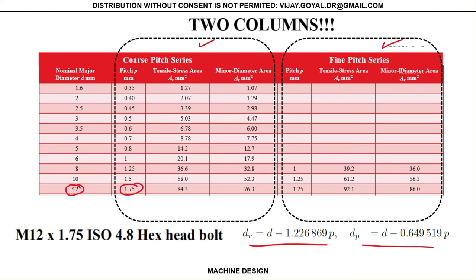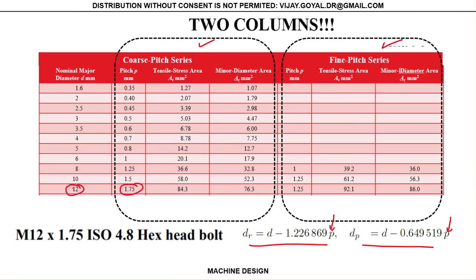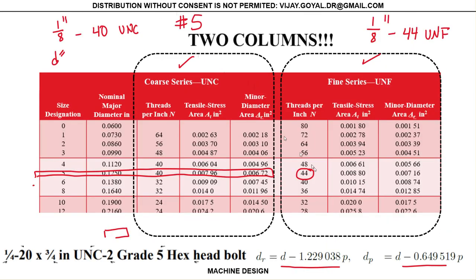Okay, and in this particular example, in this particular screw, this is easy to find because you already know this, and this is given by the pitch diameter, so just use this equation. Okay, and note that the number is correct, but the only change is this one, 0.38. And by the way, this is table 8.1 and 8.2 of your textbook.